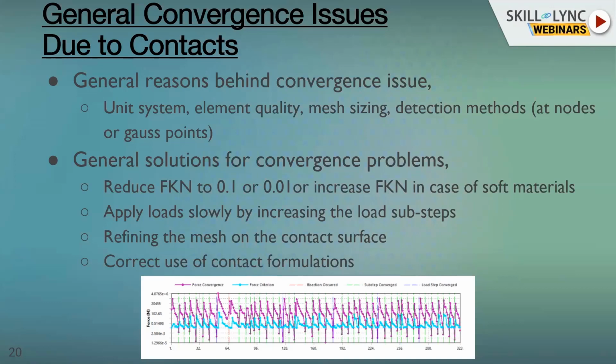Then element quality. You need to make sure that elements are of good quality when there is a contact. Big elements with very few nodes will not give you convergence, or will not give you a fair contact force distribution when the contacts are defined in the problem.